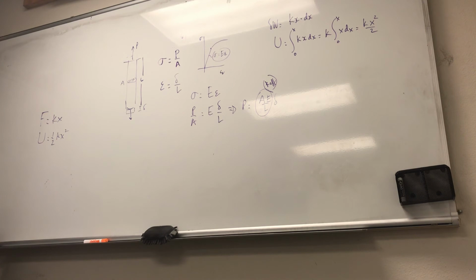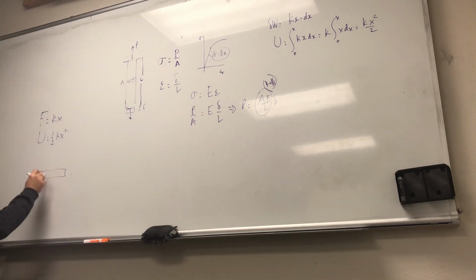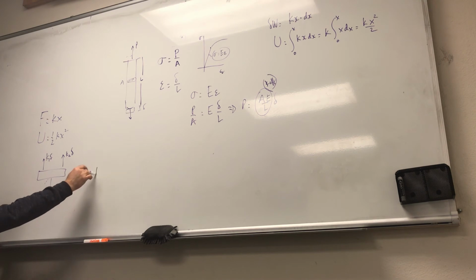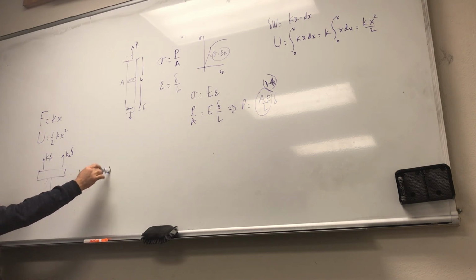what do they share? Displacement? They share displacement, exactly. So if you pull, for example, with a load W, as you see here, right? If I were to do a free body diagram, what do I get? I get W pushing down like this, right? And then what is the force going this way? It's K1 times the displacement delta, right? And this one is K2 delta. So what can I say then? I can say that W is equal to K1 plus K2 times delta.